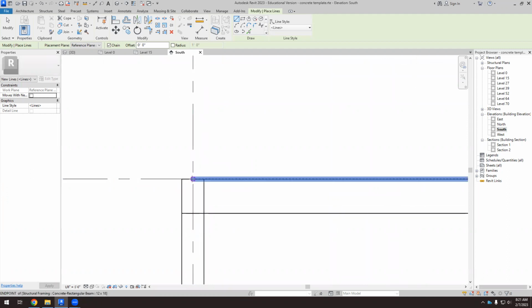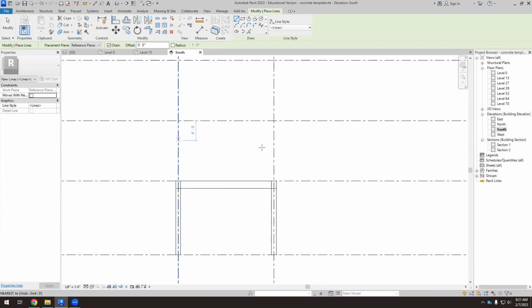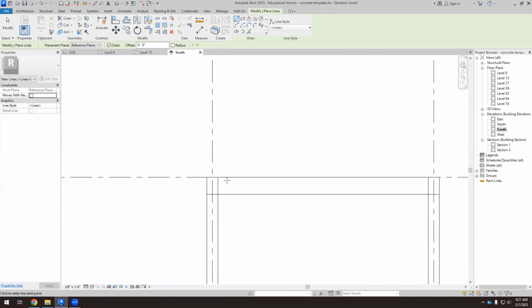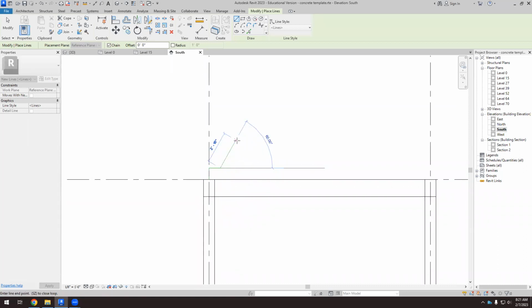It's important because I'm going to draw something and then I'm going to copy it different times. So the reference point for copying things is going to be the axis, the vertical grid line. Okay, so I have to start this shape from this point. So I go 1 foot up, 1 foot in this direction. And then if that angle is 30, that means that this angle has to be 60. So we go 60 like this.